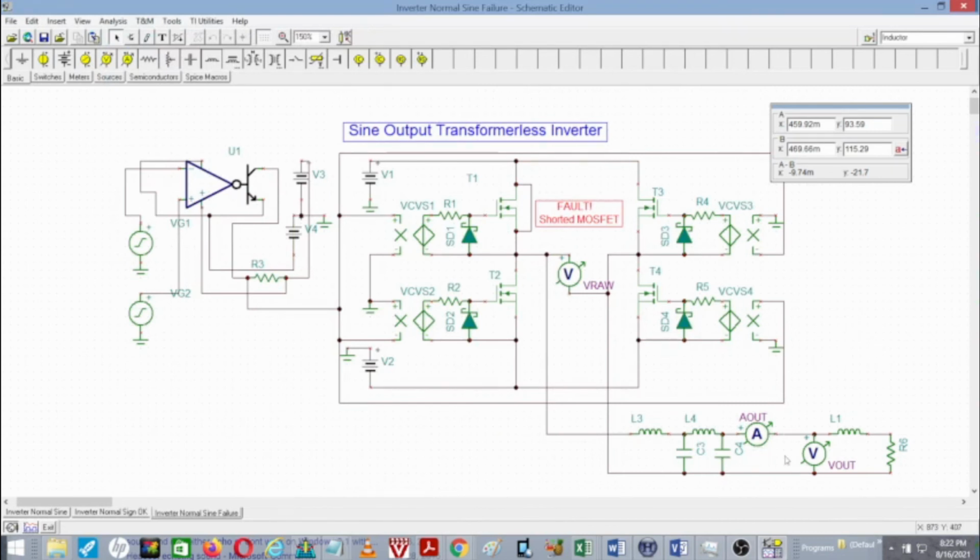And again, a manufacturer who wants to make a top-tier transformerless inverter is also going to include a relay in this output circuit. That relay will only be turned on when the inverter is delivering a correct output. If the circuit detects that it's deviating from the correct sine wave, or that there's a DC component, it will shut the relay off.